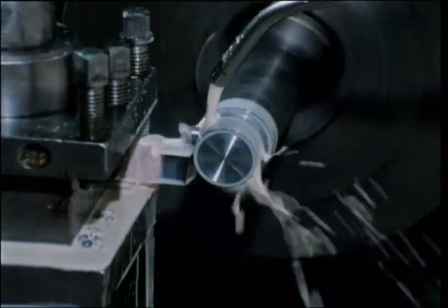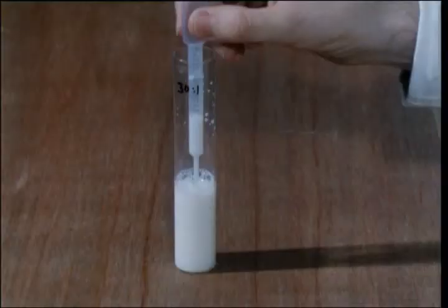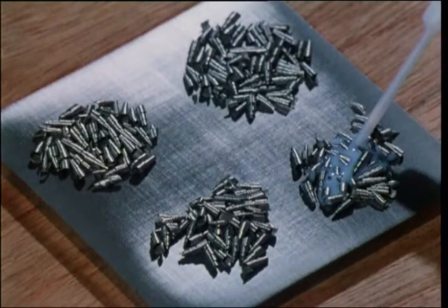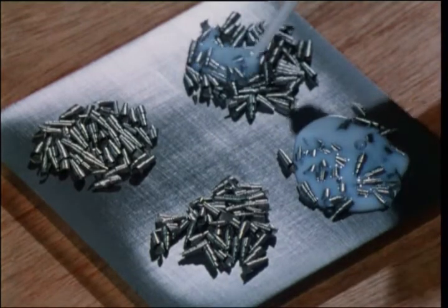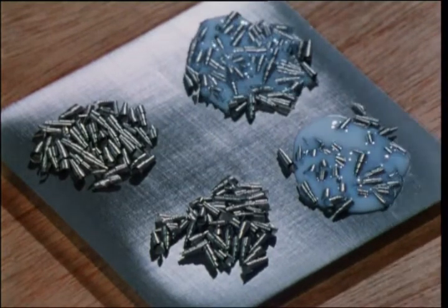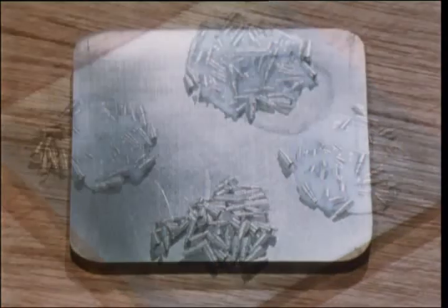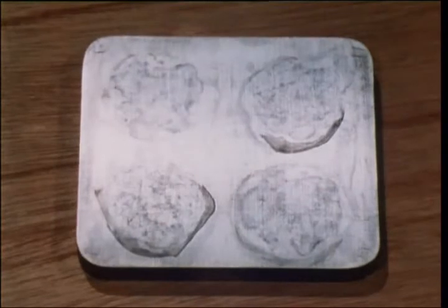Cutting fluids often contain dissolved oxygen and water. An inhibited cutting oil emulsion is tested on steel swarf on a cast iron plate. The resulting corrosion, after a set period, is evaluated. This checks not only the protection of the cutting machine and tools, but also of the manufactured components.